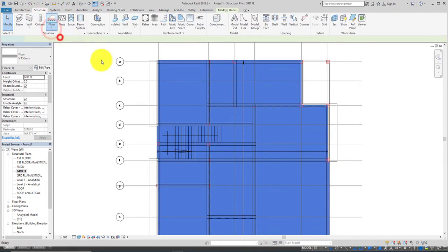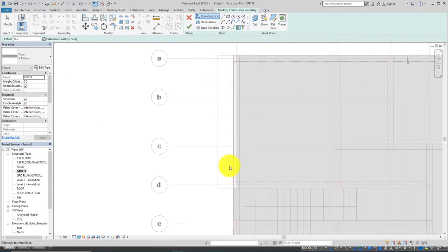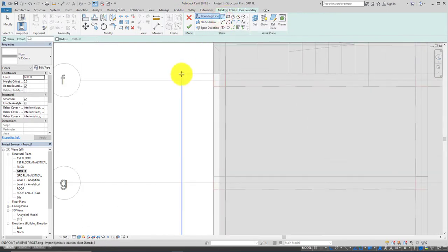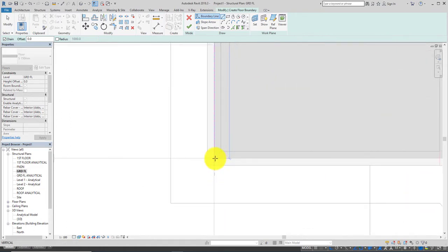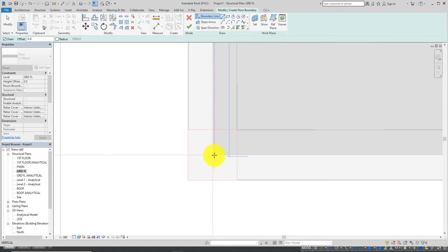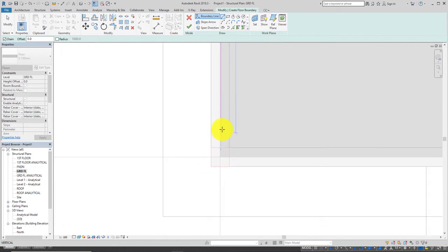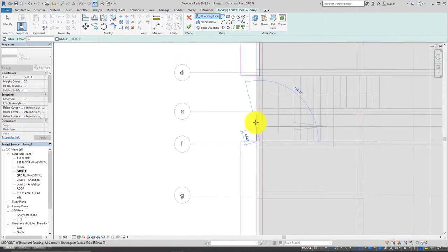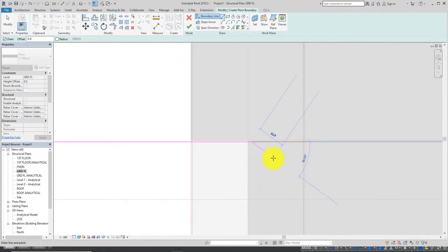So we say floor, go to structure. We need to draw a floor here, a cantilevered floor. So we say this, we pick from this point, since it's rectangular, to this point. So we have that. We can pick on our line so that we'll be able to form the rest of the floor at once. To have it, drag it down. It comes to this point. Let's see it. It's going to overlap. Let's see. Are we picking it at the right point?